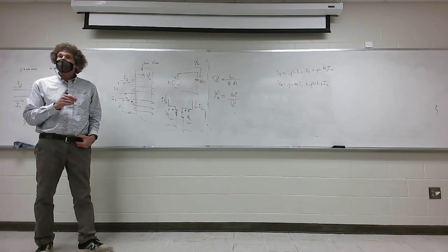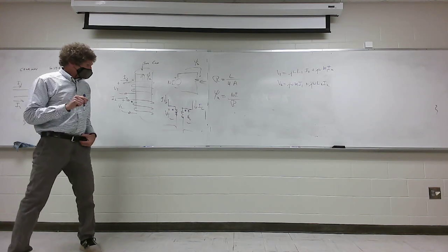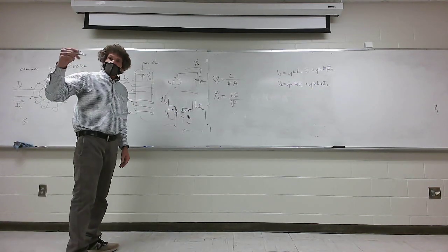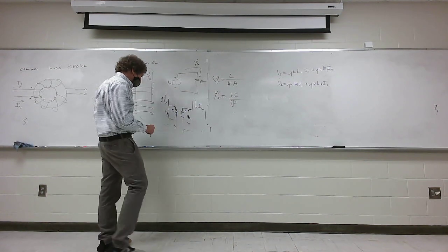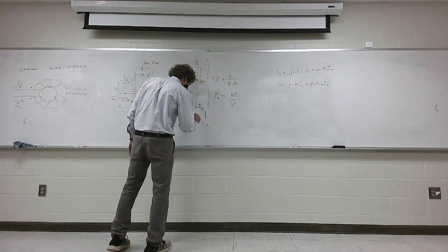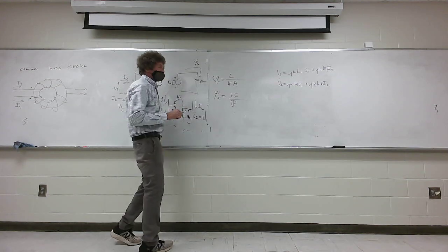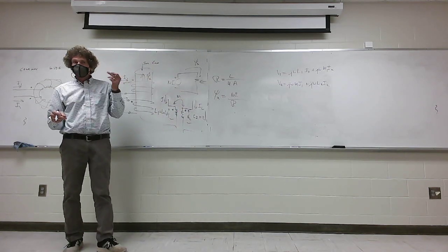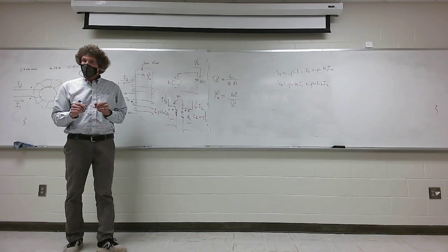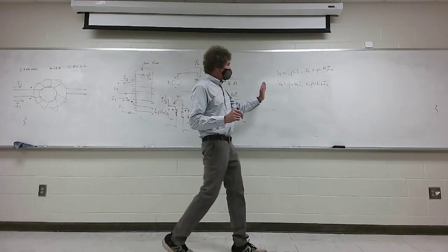Y'all remember that? Okay, now we get into this circuit right here, which is the same thing as I've shown there. And when you do any of these common mode chokes, you assume L1 equals L2, and the mutual is going to approach the value of the actual self-inductance. Now there's a very important reason for that. You're about to see it. Everybody got me on this, class? So now we come to this.